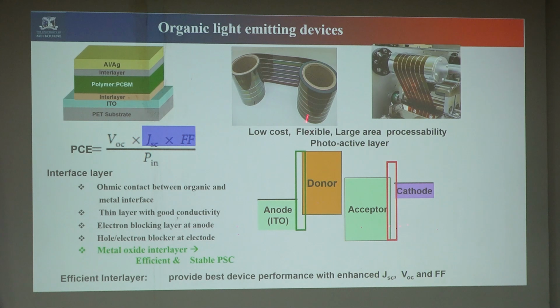So we have the electron blocking layer on this side. Similarly, on the other side, we want to extract only electrons, but the holes can also come over there. That should be blocked to have better, more efficient performance. Otherwise, if the holes come to this side, they will recombine and reduce the performance, particularly the energy levels.